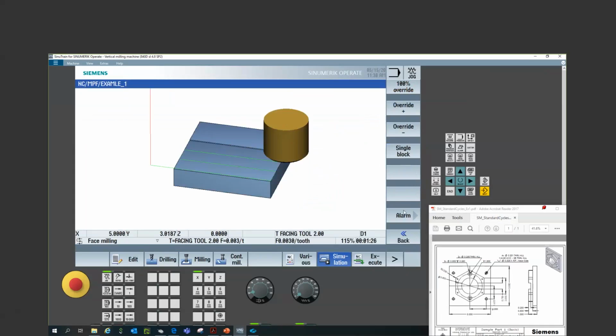So we can control the speed by these override keys here, and that's displayed here in the lower right hand corner. Right now it's at 55%. We can speed it up, we can go to 100, or if you have a keyboard, you can do Control M, and then that automatically toggles it back up to 120%. And if you do Control M again, then it goes back to wherever the last override percentage was set at. Okay.